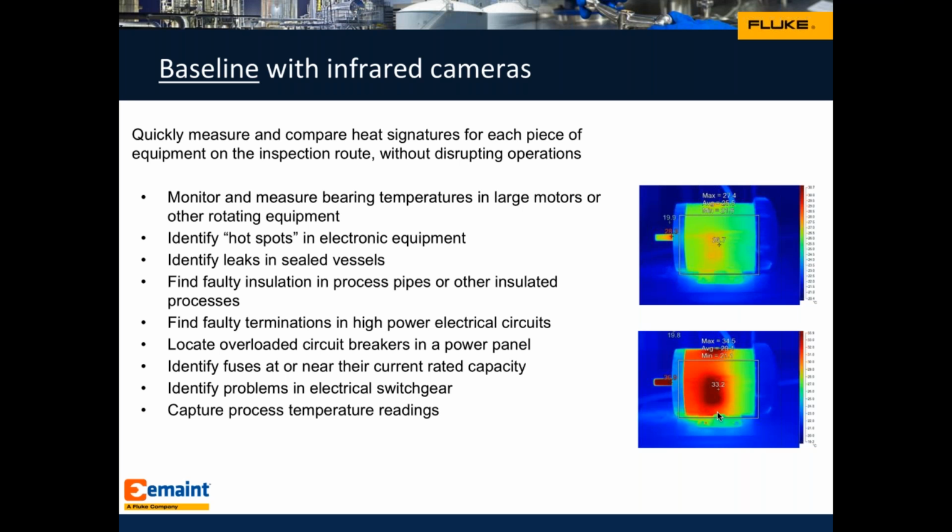Do a baseline with an infrared camera. That's often an easy way to do it. You take your camera. We often explain to customers, hey, why don't you go and look at all your motors, all your pumps, all your electrical panels, anything for that matter. You can look if you have any leaks, if you have any issues with the buildings, or the tank levels. I mean, there's a number of things you can take a picture of from a thermal camera aspect.